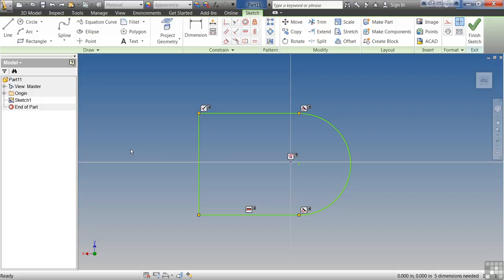Those of you who are familiar with AutoCAD may find it doesn't seem intuitive to design this way. In AutoCAD, you had to draw everything out and create these precise sketches that didn't have any intelligence in them. So you could only do it the one time, and then you had to go back and manually modify stuff. In Inventor, you get the design intent first by sketching out your basic shape, and then you start refining that design intent by adding geometric constraints, and then later dimensional constraints.